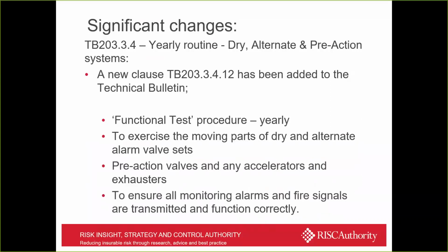And this also allows for alarms to be tested, but it doesn't necessarily mean every year that you have to flood the system and do an actual sort of simulated fire test to trip the valve. And we felt that annually that could be a little unnecessary, given that by flooding the system you've got a problem then in draining the system off and recommissioning it.